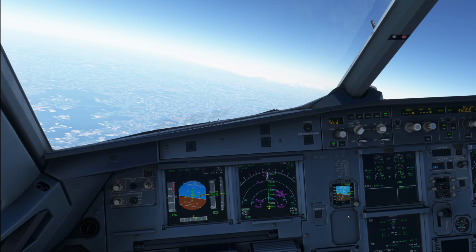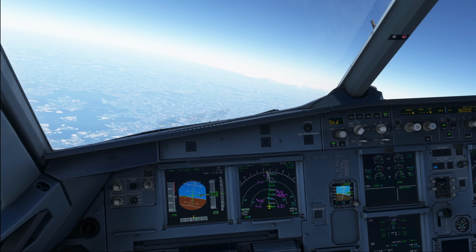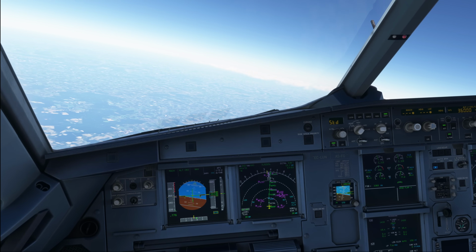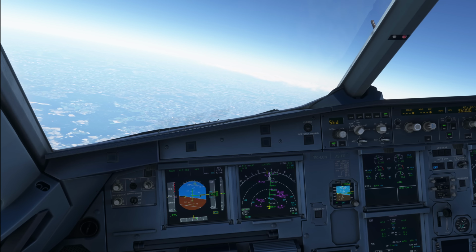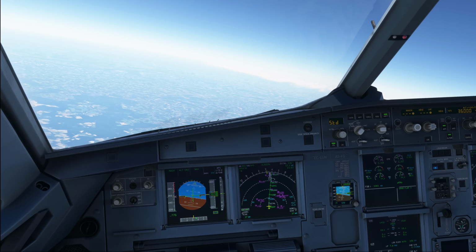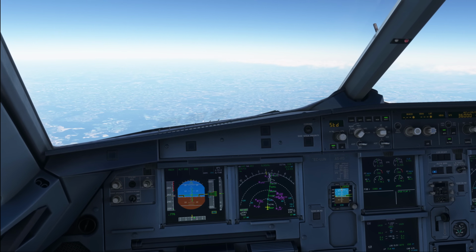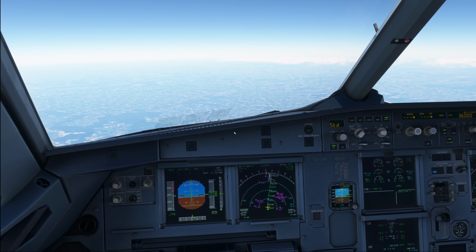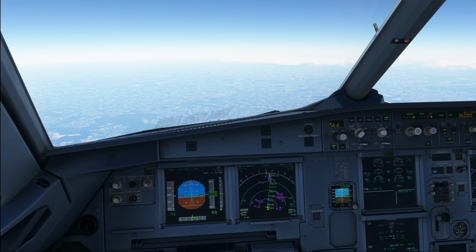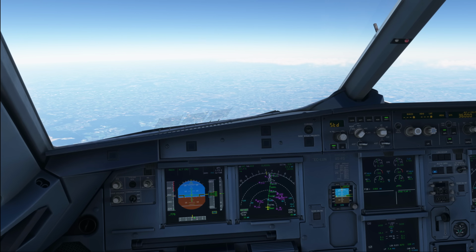Now, likewise, noise abatement procedure 2 therefore is the favorite noise abatement procedure in order to save money in terms of saving fuel, because you can accelerate at a lower altitude. NADP 1 and 2 are the most used ones, and NADP 2 is the default procedure that you will normally use, so acceleration and thrust reduction at 1,000 feet above the airport.